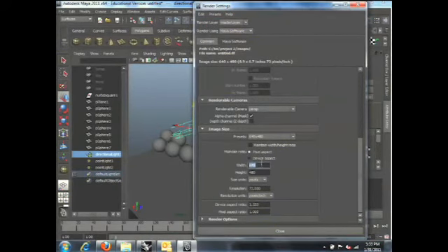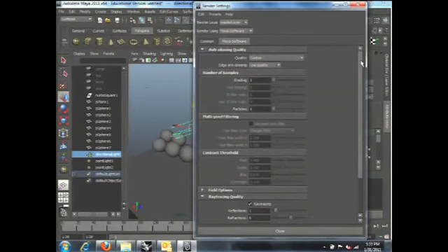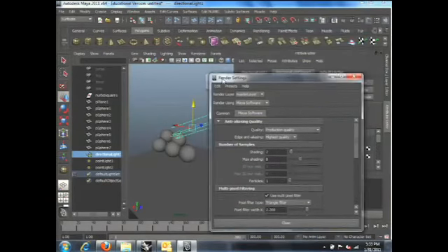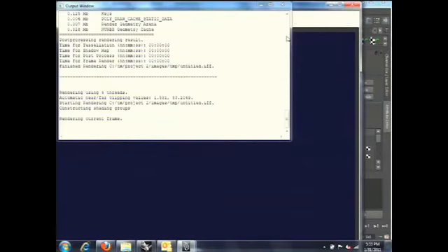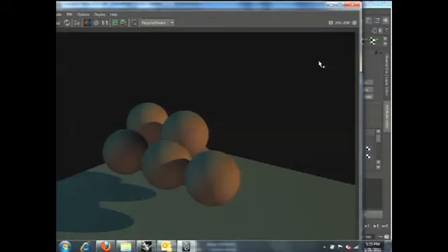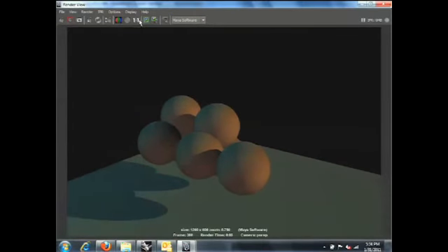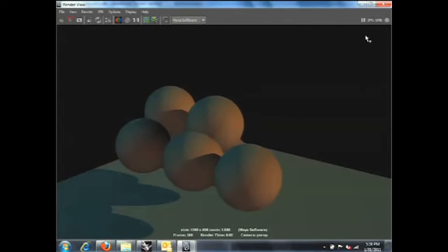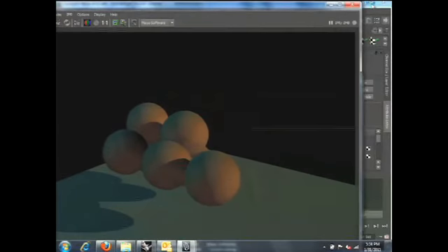You can also set up resolution exactly the same as Mental Ray. So here I can increase the resolution. Let's give 1200 by 800. In the Maya software tab, here I can set the quality to production quality. So this will take a longer time, but it's more accurate. All right, so now let's do the rendering. You see it's taking a longer time, right? I use the Maya software rendering if Mental Ray crashes. If you have really complex geometry, you have to use software rendering. It's quicker.